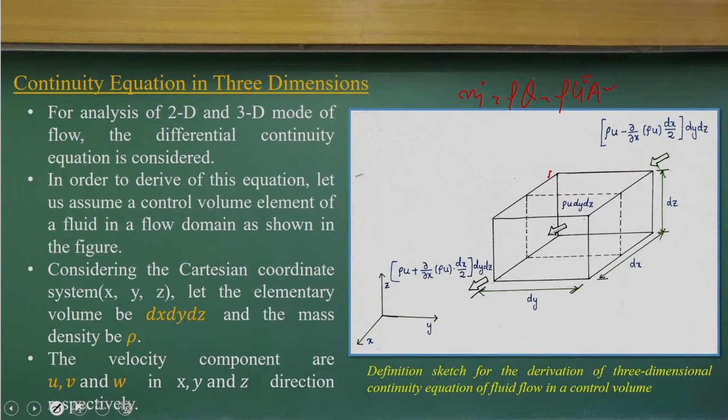So the basic concept we are using is that the mass flux is equal to rho into Q, and in terms of velocity, rho u A, where A is the surface area. So, I can compute the mass flux passing through a control surface as a function of density, the velocity scalar component and the area. That is a very basic thing.